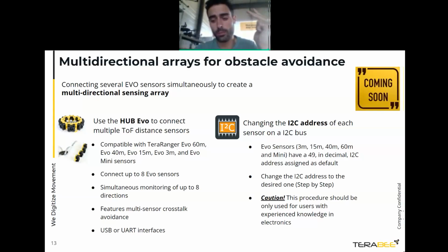But if you have the I2C or the UART backboard, you will need a system in the middle, a TTL, which transforms the I2C and the UART to USB, and it can be connected to the computer directly, because we can do it only using our GUI through the computer. Then follow the step by step procedure.